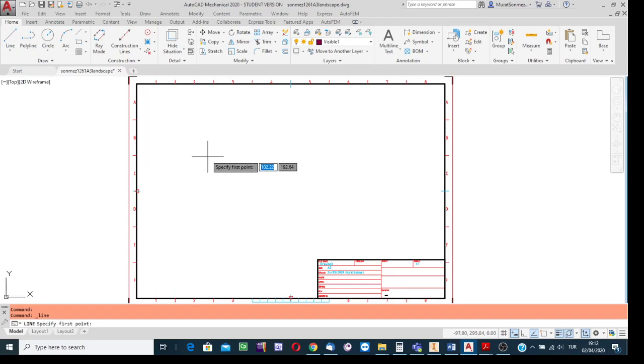And then the system asks for the location of the starting point. You see, since the dynamic input button, which is along the status bar, over here, is on, my cursor indicates that. Whenever we start a process, it is always true. In the vicinity of the cursor, we find some rectangles in sequence. It looks like, as I said already, a train.